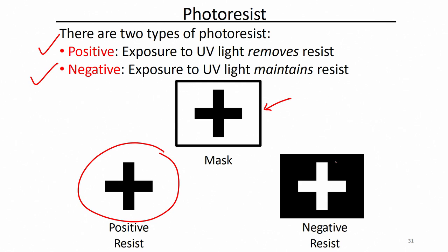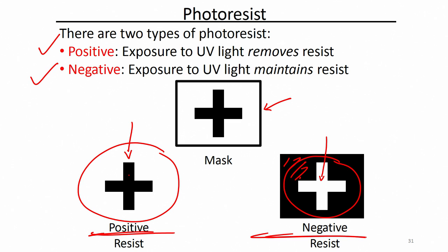In negative photoresist, the opposite will happen. That means, if you consider that this is a mask and the whole wafer was coated with photoresist, then only this area was protected, that means only this area has photoresist. In the other case, everywhere there is photoresist except this area, absolutely opposite of each other, that is why this is positive and this is negative. Alright, excellent, easy, super easy.